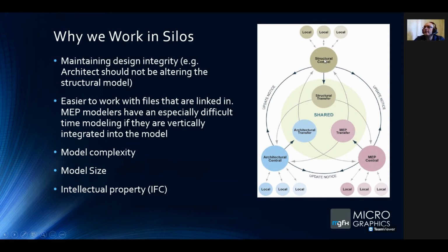But on Civil 3D, what we are able to do is to create data shortcuts to things like topographies, elevations, alignments, and the like, where each one of those can be represented as a separate file, which then makes up the ultimate infrastructure project. So in mining, they also use Civil 3D, so that, at least from my perspective, is something where collaboration is possible. The data shortcuts can be saved onto the cloud. They are XML files and are hosted on the cloud.